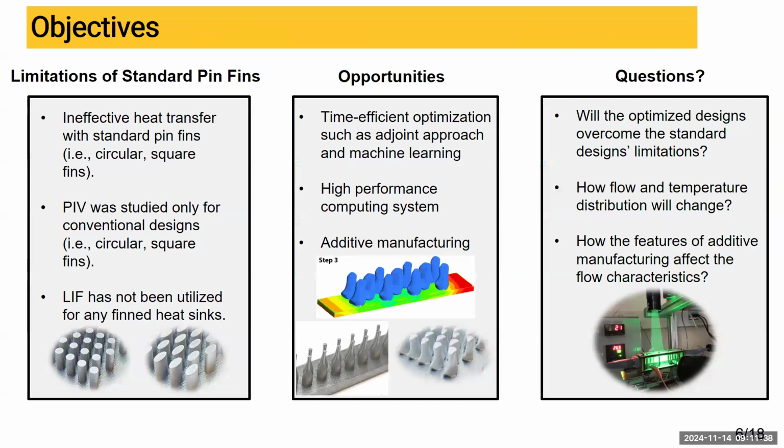Now we know the standard pin fins are ineffective in heat transfer, and simply increasing the size of the fin may not enhance the thermal efficiency since the pressure drop also increases. However, people still use them because of the limitation of conventional manufacturing methods like CNC or casting. This is the biggest advantage of additive manufacturing: it enables the fabrication of complex designs, and the widespread adoption of